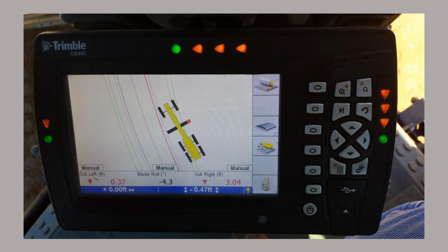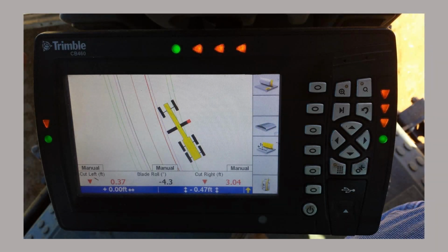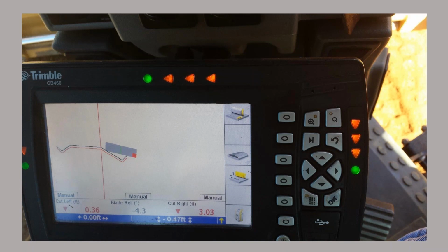And so if they're cutting a lot, let's say they've got to cut 3-4 feet out, you can't just dig that blade in and say, hey, just let it go automatically. So they'll drive by, take out some, and they'll keep watching. Then when they get within maybe an inch or a half inch from where they're supposed to be, they can put it in full automatic and just let the machine get operated by the model itself, which is kind of neat. And then there's a bunch of different views.